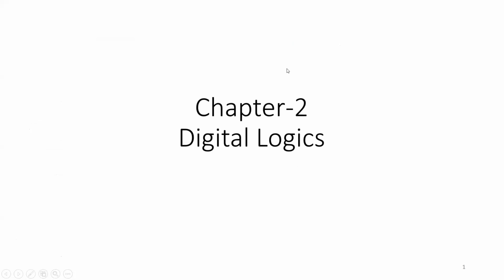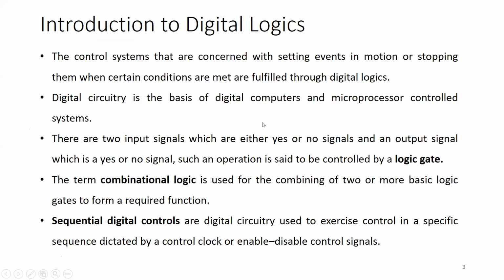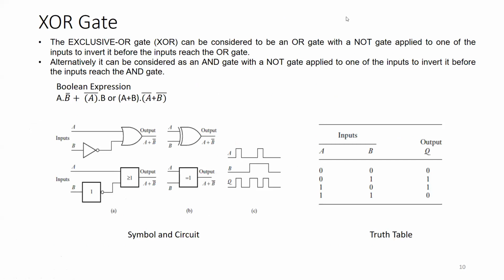Yes, sir. So have you gone through any example of XOR gate as we have discussed yesterday? Where can we use an XOR gate? The unique truth table applicable to an XOR gate is that you will get the output only when one of the inputs is provided. Otherwise, if there is no input, or if both inputs are present, the output will be off or zero. So have you come up with any example on the internet? Have you gone through it or not?